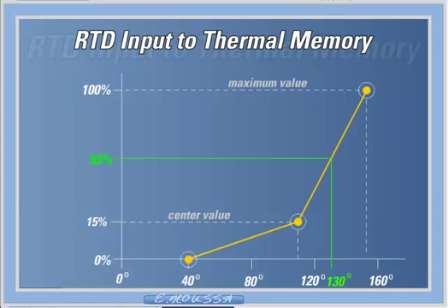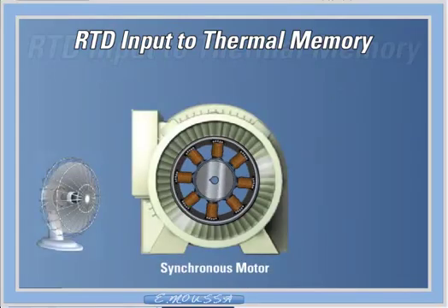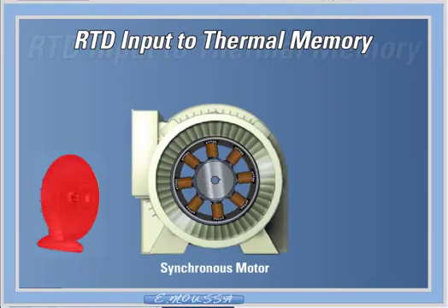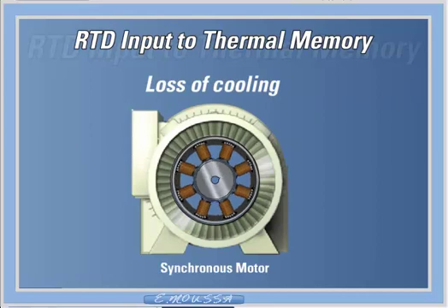This thermal capacity would then be used if the thermal capacity used from the overload calculation was less. This feedback provides additional protection when errors have been introduced, such as when the cooling has been lost, or incorrect selection of the overload or the ambient temperature is unusually high, etc.